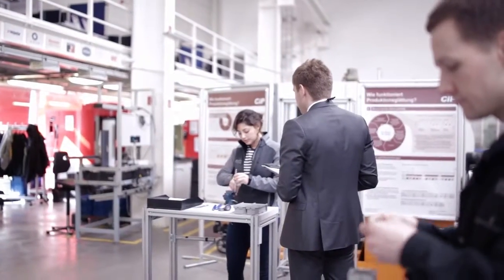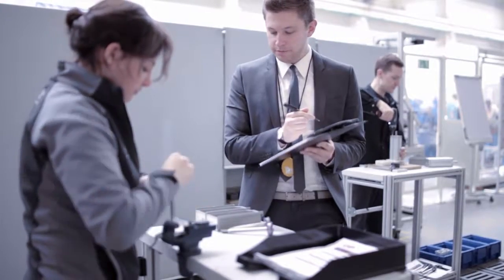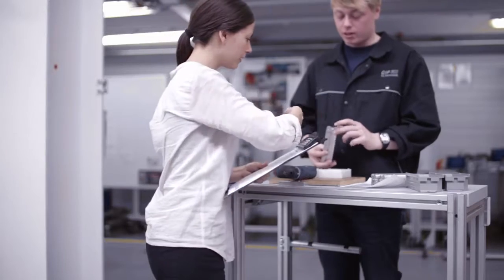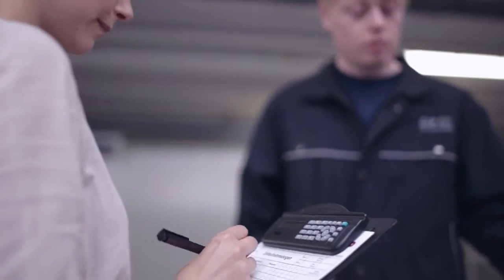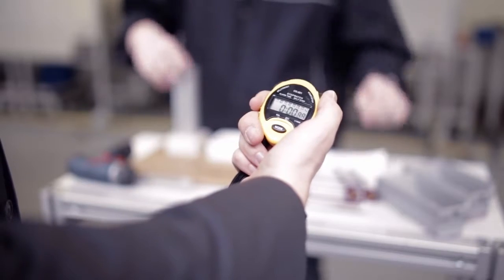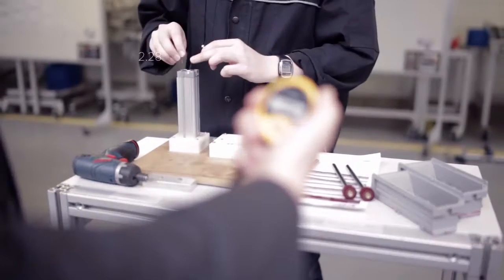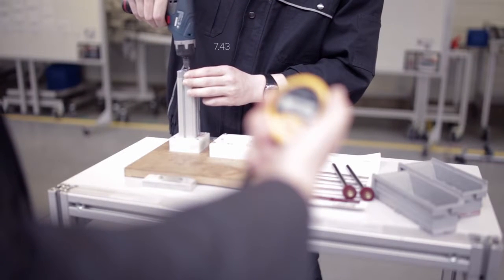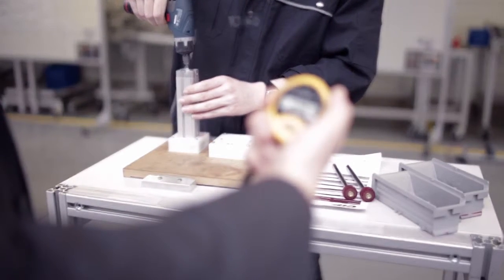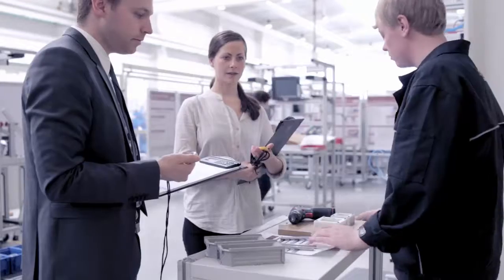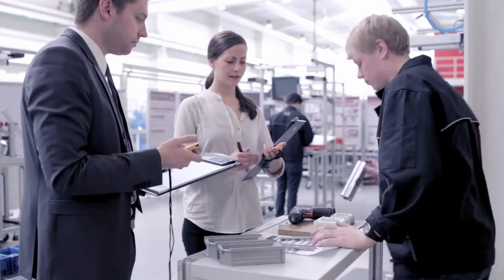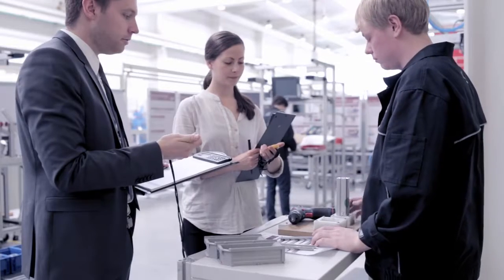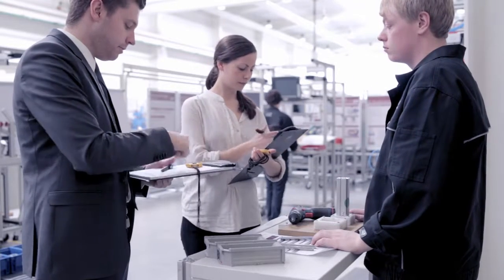First, the individual tasks in the assembly are documented. From this, the assembly plan is generated. Subsequently, the necessary process time for each individual task of the assembly is determined. This can be determined either using an analytical method, such as real-time measurement, or, in cases of a new system planning, synthetic methods such as MTM.